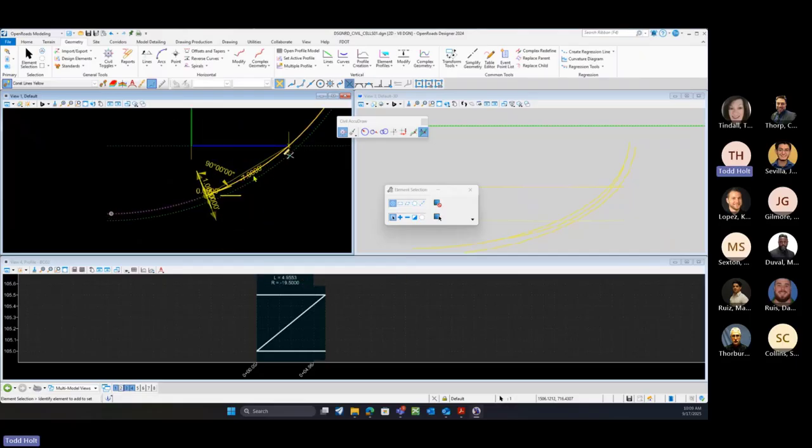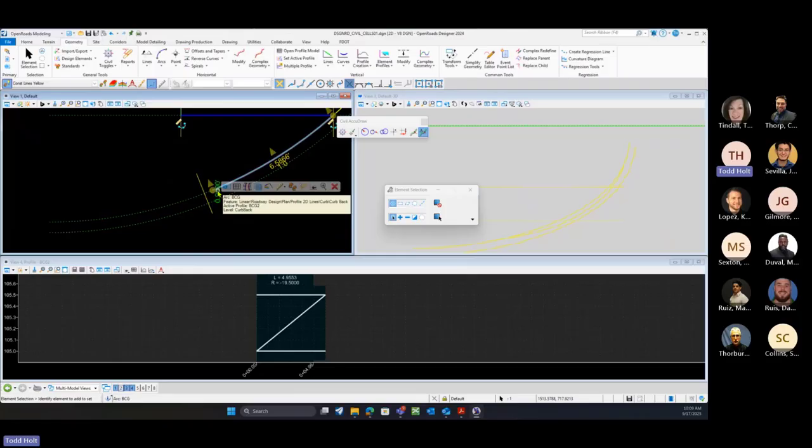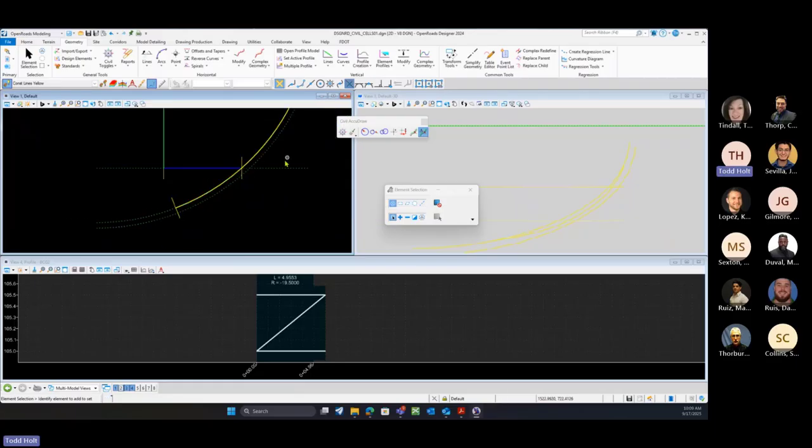I'm going to do the same thing. I can turn off solo AccuDraw, and grab this line now. And this one, since it's a start, I need to grab this arrow, and I'm going to snap to that intersection. So now I have the controls built in. If I want to make the adjustments here, -8, that's going to reestablish on there. So I'm building in the control of how I want that to rule. I'm done with civil AccuDraw, but Delta Station's a cool tool that you can use to build in rules to that civil stuff.